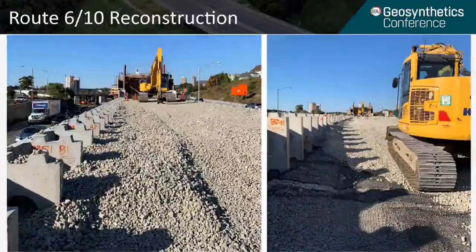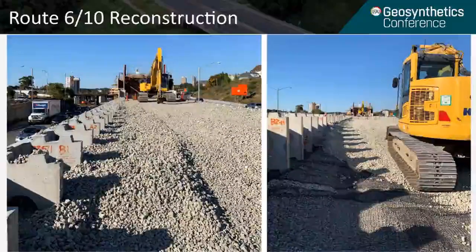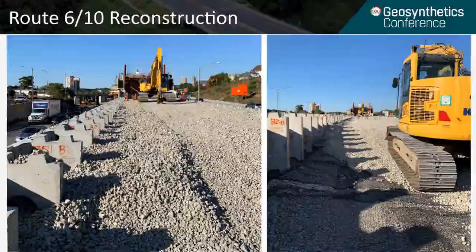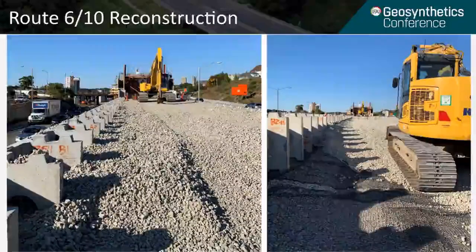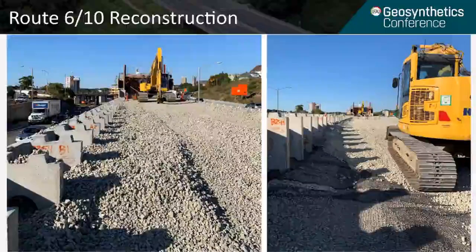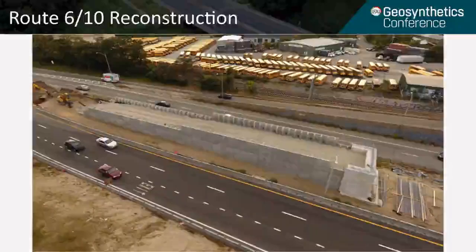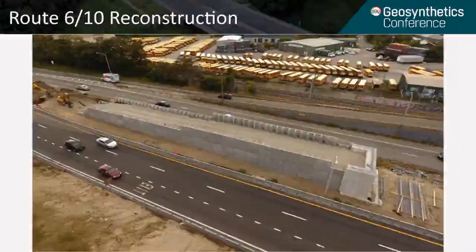This slide shows you two photographs from the ramp construction. You can very clearly see the biaxial geogrid that's used as reinforcement in the right-hand photo. That excavator that's shown is the primary equipment that was doing the placement and compaction of the foam glass. And finally, we have another aerial photograph showing you the completed ramp about halfway up to the final abutment height. The final abutment height for this ramp was about 36 feet.